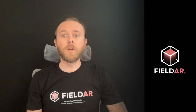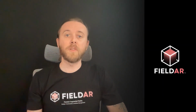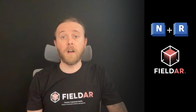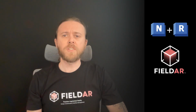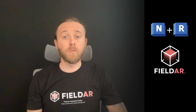In this video, we're going to cover uploading building information models, or BIM, using the FieldAR plugin for Navisworks and Revit. The recommended workflow for uploading very large BIM to FieldAR is to section your model into separate chunks, and have each chunk associated with your QR code target at the job site. Each chunk can be an individual floor, zone, or even as small as a single room.